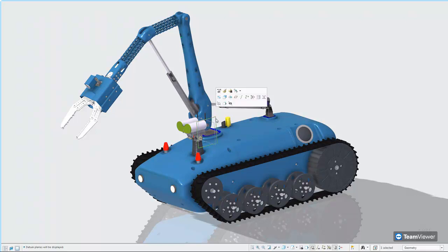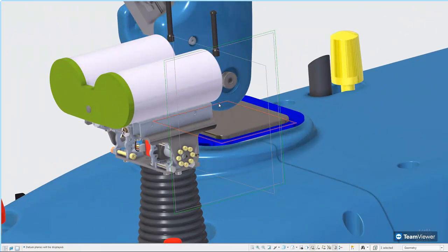So some of the features we'll see is I can select this datum plane, and a nice new tool here is zoom to selected. So we have new context sensitive menus that just by selecting them will give you this option. Here I can say zoom to that selected datum plane, takes me into that immersive environment for me to actually see it.